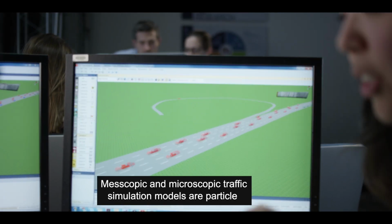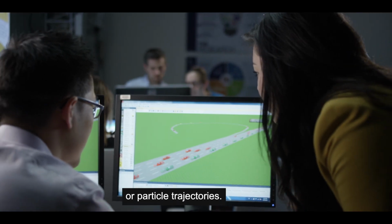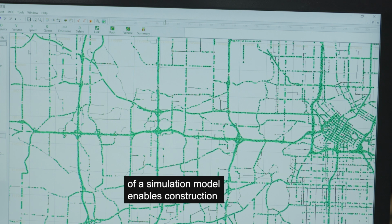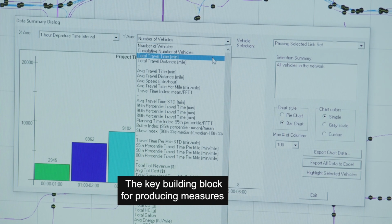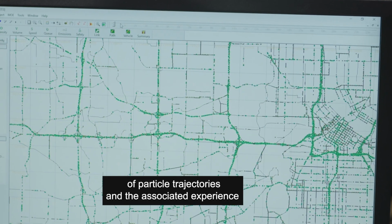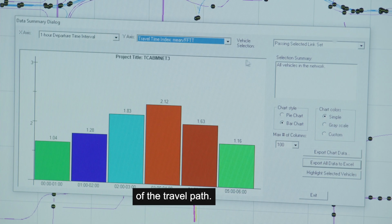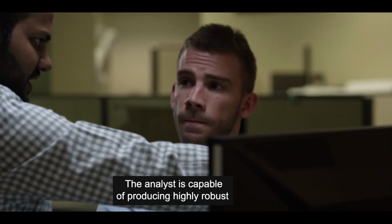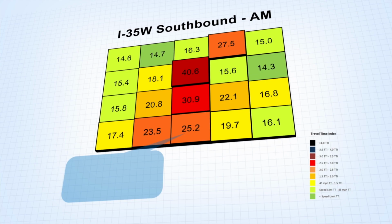Mesoscopic and microscopic traffic simulation models are particle-based models that produce individual vehicle or particle trajectories. The availability of trajectories in the output of a simulation model enables construction of any level of travel time distributions of interest. The key building block for producing measures of reliability in this framework consists of particle trajectories and the associated experienced traversal times through entirety or part of the travel path. With the appropriate methods and tools to process extensive microsimulation outputs, the analyst is capable of producing highly robust and informative results on travel time performance.